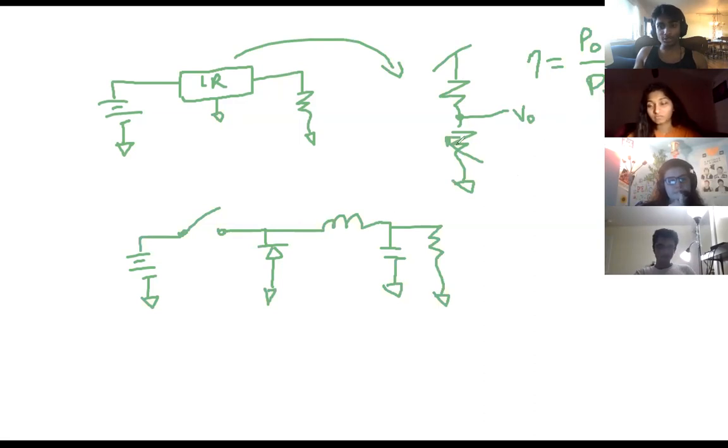We don't experience the same magnitude of conduction losses in a buck converter because when we're not using excess energy, the switch is open, right? We do still experience conduction losses because when the switch is closed, there is some non-zero resistance across the switch. It is much smaller than a resistor because a resistor necessarily resists, whereas a switch is much lower resistance.